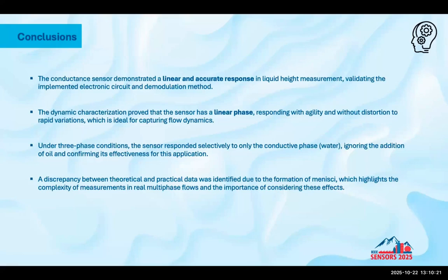For conclusions, the conductive sensor demonstrated a linear and accurate response in liquid height measurements. The dynamic characterization showed the sensor has a linear phase. And in the three-phase condition, the sensor response is selective to only the conductive phase, as I expected.